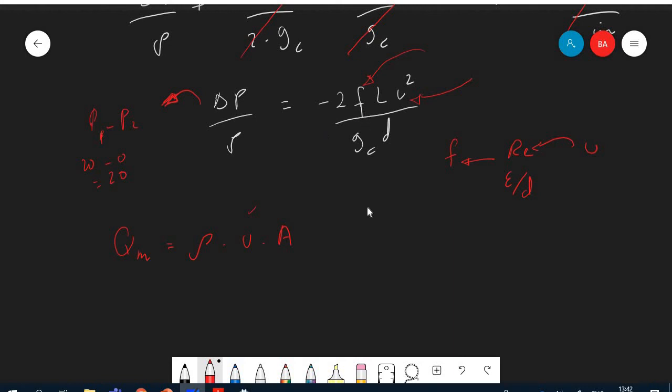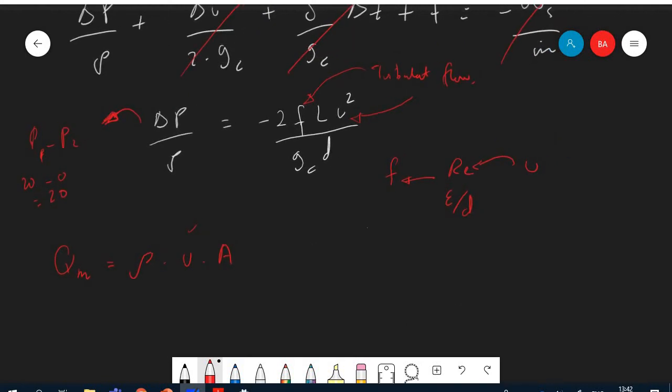And here for f, we have what is really turbulent flow. So maybe we have a way to calculate f as well. Of course, we still need some numbers to substitute. If it is totally turbulent flow, and that is just an assumption, by looking at the 20 bar we are saying 20 bar sounds like a fully turbulent flow.